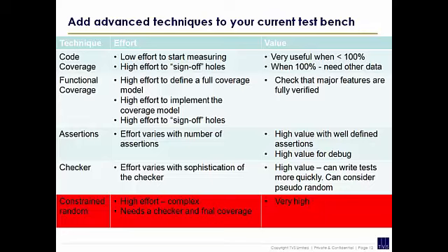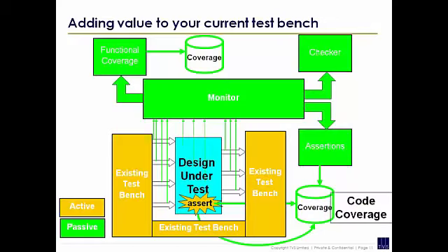And the checkers, these checkers here can be quite complex to write. They're written at a high level of abstraction. They need to be written at a high level of abstraction. Some people write them in C, so you can do a reasonably quick model of an I2C. So the I2C is written in VHDL or Verilog, and your checker is written in C. It's a very high abstract model. It just says if the transaction goes in, what do I expect to get out? If I write to an address and then read back from that address, I expect the same data to come out.